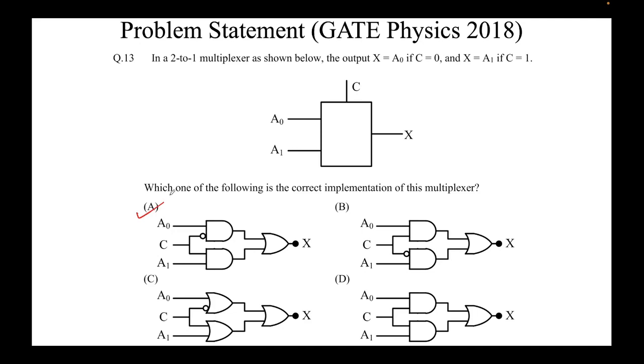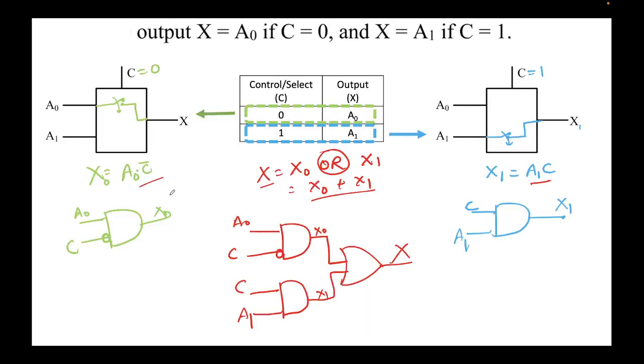Multiplexers are actually very important in real life circuits, as well as for the sake of your examination. These are very straightforward ones. The 2:1 multiplexer is the simplest multiplexer that we can make, and you should also try some 4:1 questions. 4:1 is slightly complex, but the concept remains the same. You should try to solve them row by row, like I've solved it here. If you go row by row, you can never go wrong.